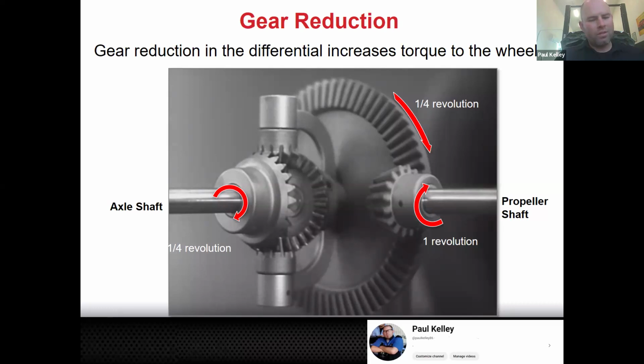You see that, right? So even if it turned a 16th backwards, if this one turned a quarter forward, it's basically like it's really just going slower. Technically, this gear will walk backwards though, but it's walking backwards slowly while this whole thing is turning forward really fast. That was the hard part, that was really hard for me to understand. So let's just give it RPMs, for simple sake. If this thing is going 100 RPMs forward and this one turns backwards 1 RPM, really what I'm saying is this axle's going 99.